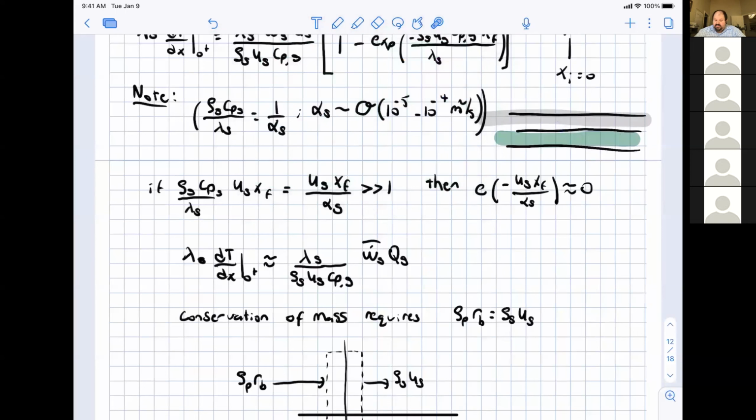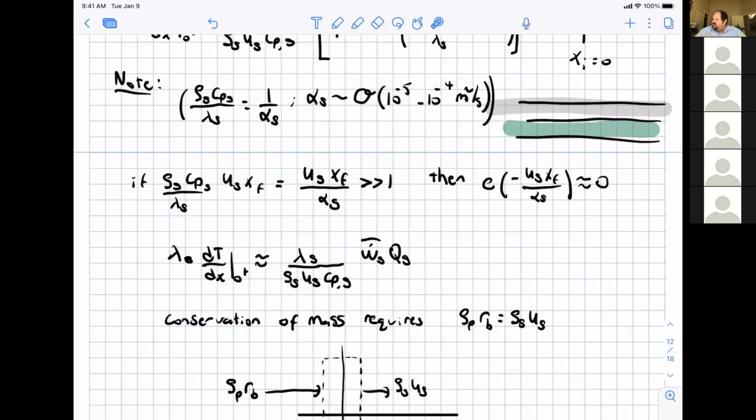The reason is quite simple: for the most part, the propellant is acting as its own insulator. You do have to be careful if there are regions where the propellant burns completely, and in those regions, you are going to have to add some insulation. But the propellant normally acts as its own insulator, so in regions that are covered by propellant during the burn of a rocket, you don't need to get carried away with insulating the back end of it.